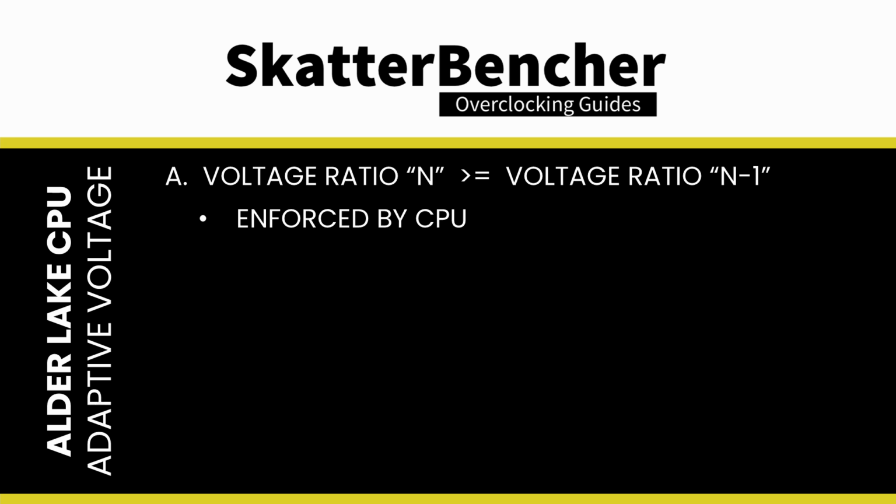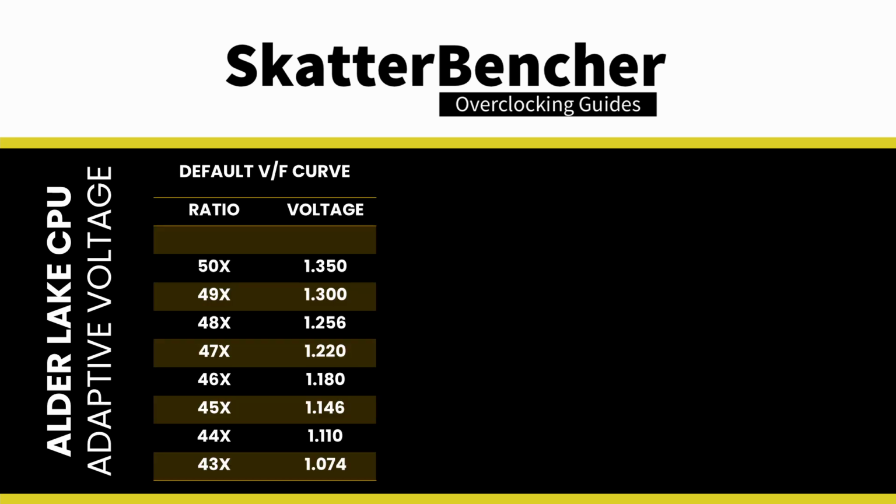There are very specific rules that govern how an adaptive voltage is set. A. The voltage set for a given ratio n must be higher than or equal to the voltage set for ratio n-1. For our 12700K, the VF curve is defined up to 50x, so the OC ratio is 51x.